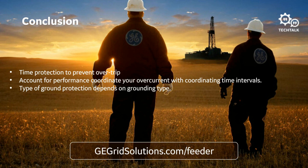So one of the questions is how do we account for poor breaker maintenance in a coordinating time interval? Well, first of all, we probably ought to have better breaker maintenance. But beyond that, we typically account for poor breaker maintenance, and the fact that we might have a 3-cycle breaker that actually takes 5 cycles to operate. We account for that performance with the safety margin.